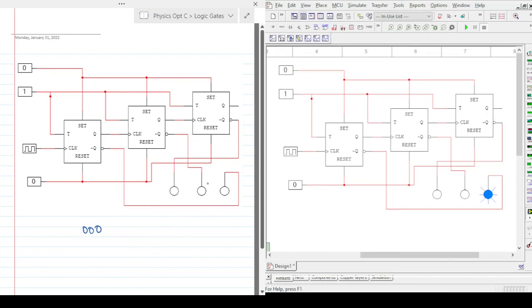It ripples very quickly. We can't see when it happens, but all of them basically change to 0. So the clock now will be on a high. It will drop to low voltage and then rise back up to high. When the clock goes from 1 to 0, nothing is going to happen because this flip-flop does not change output when the clock drops, when the clock goes through a falling edge.